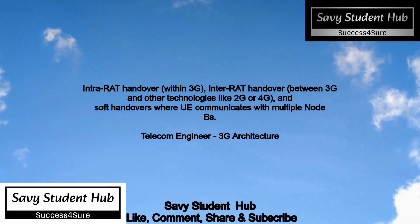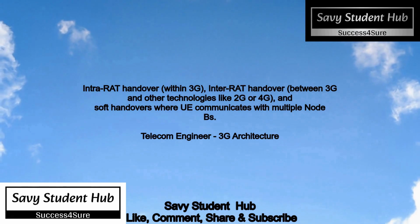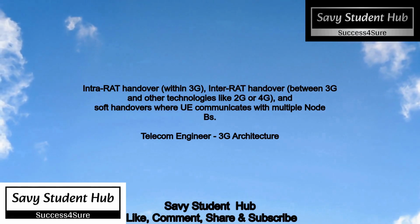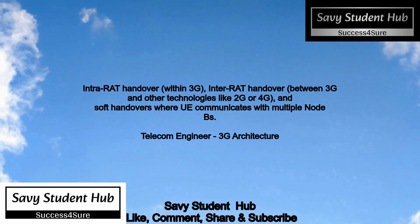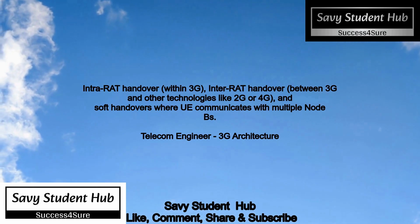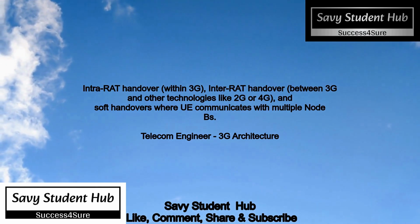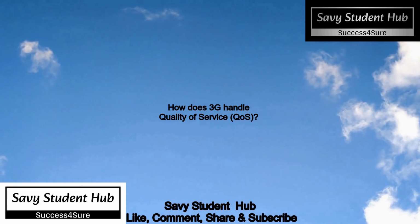Intra-RAT handover, within 3G. Inter-RAT handover, between 3G and other technologies like 2G or 4G. And soft handovers, where UE communicates with multiple Node Bs. How does 3G handle quality of service, QoS?